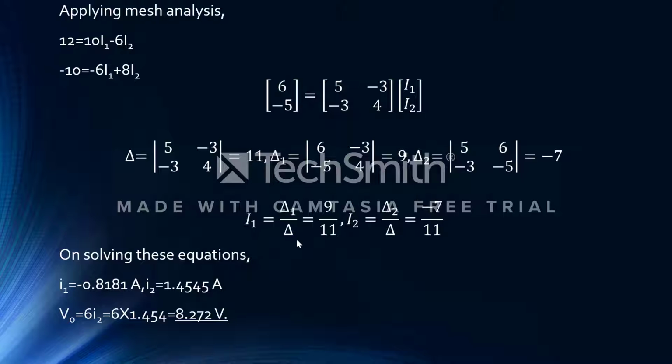By using matrices, you can solve any kind of equations, any three simultaneous equations or two simultaneous equations, very easily. So I1 is delta 1 by delta, which is equal to 9 by 11. And now for I2, that is nothing but delta 2 by delta, which is minus 7 by 11. On solving these equations, we get I1 as minus 0.8181 ampere and I2 as 1.4545 ampere.